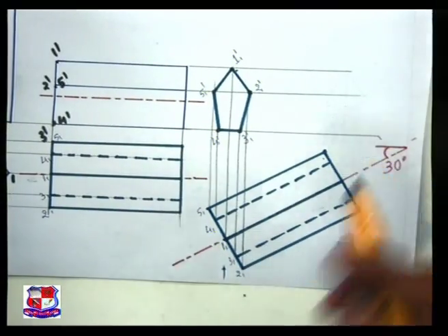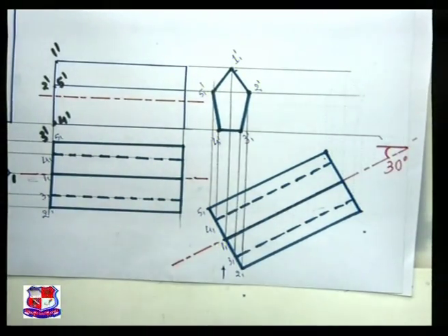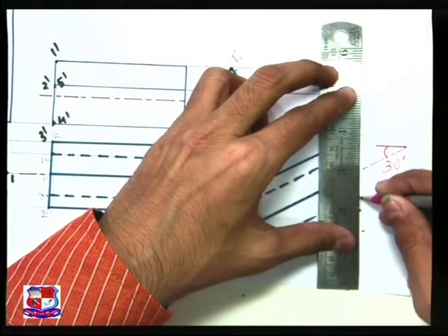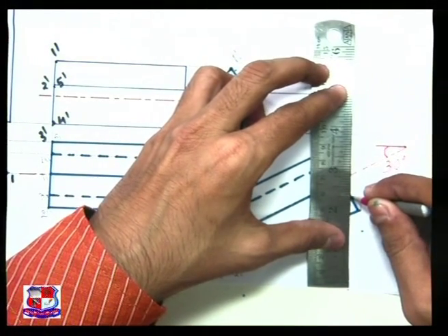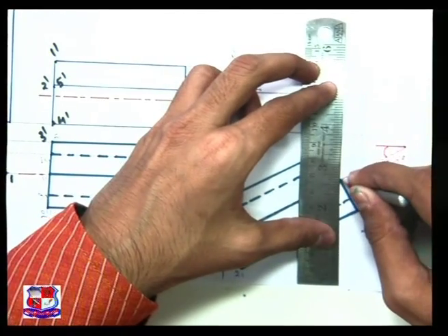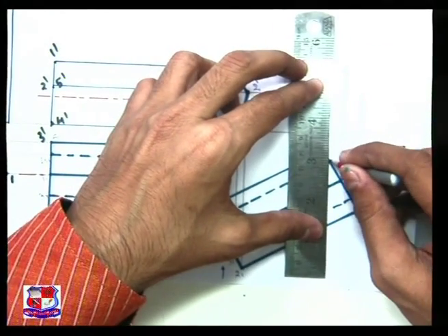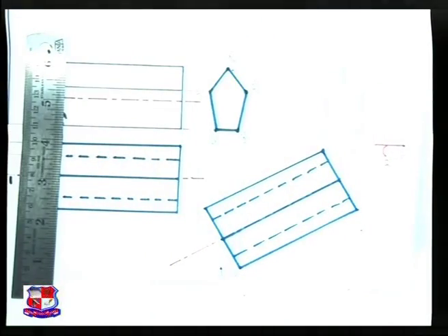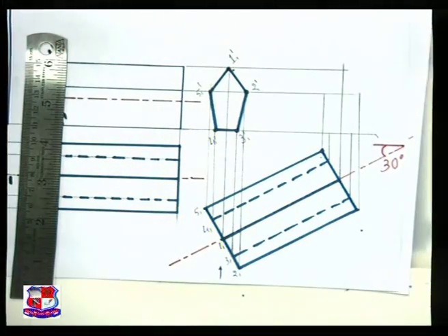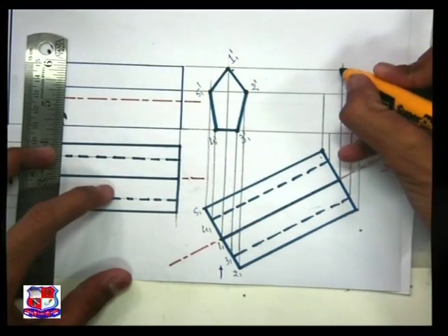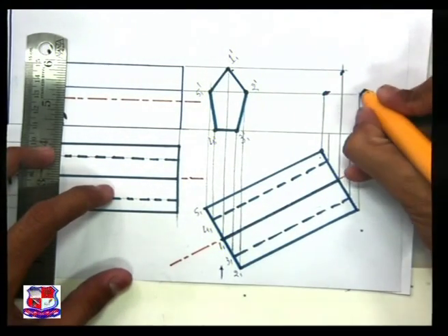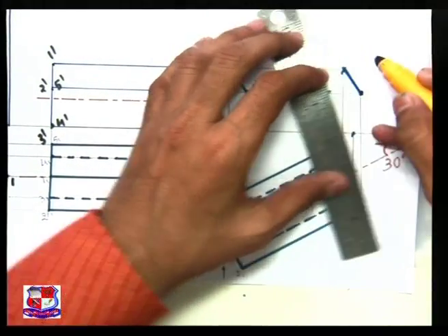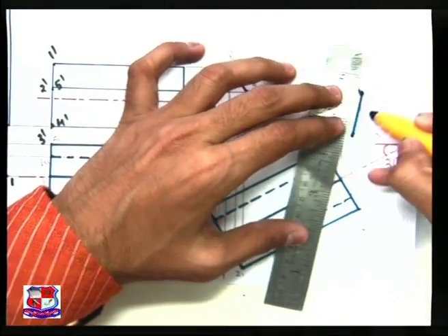Now what about this backward face? For that also draw projection lines from each end point and find out the points of intersection. Locate these points. So these points are these 5 points, 1 2 3 4 and 5, and join them with a straight line. Now what do you say about the visibility of all these edges?